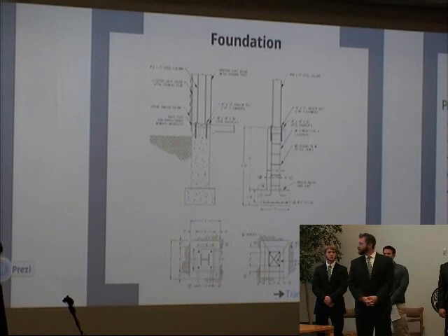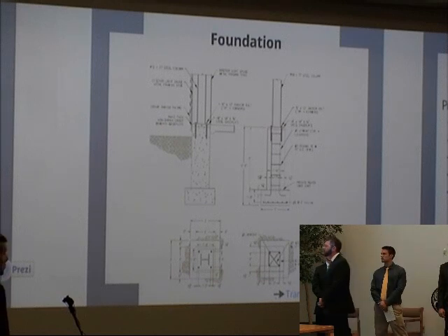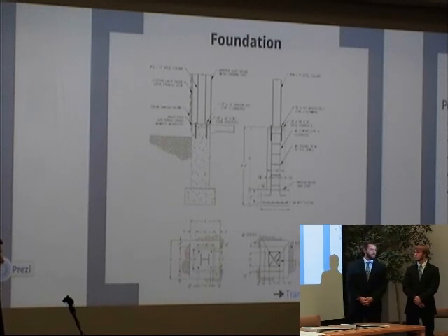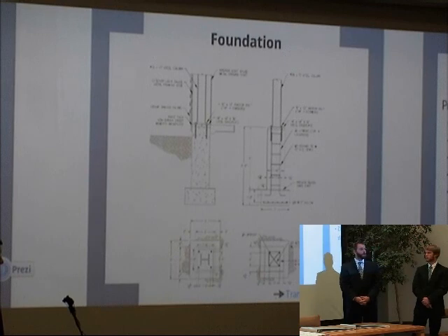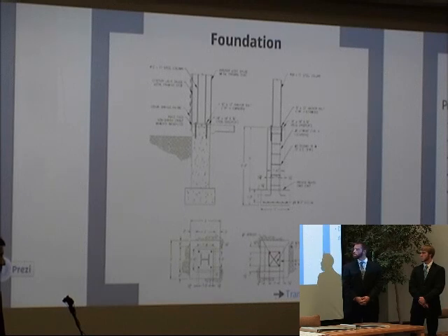For this reason, and for the constructability of these footings, 12-inch lifts of soil are going to be put in beneath them and compacted to 95% relative density. This is going to eliminate any chance of settlement in the sand, so there really isn't going to be any settlement underneath any of these footings.